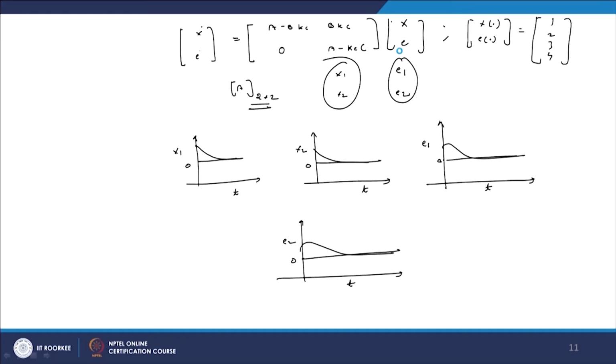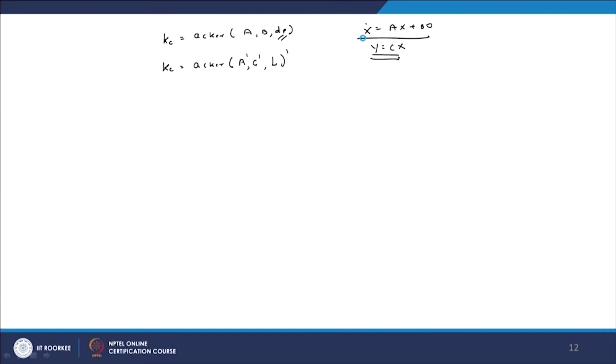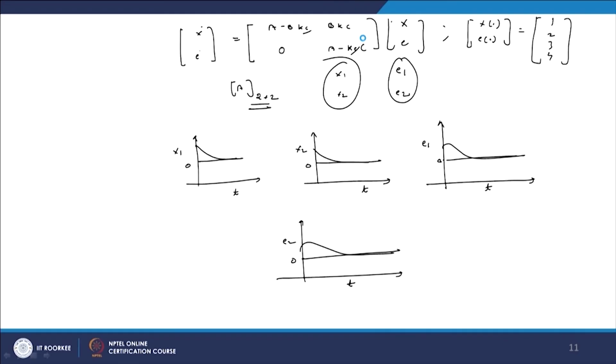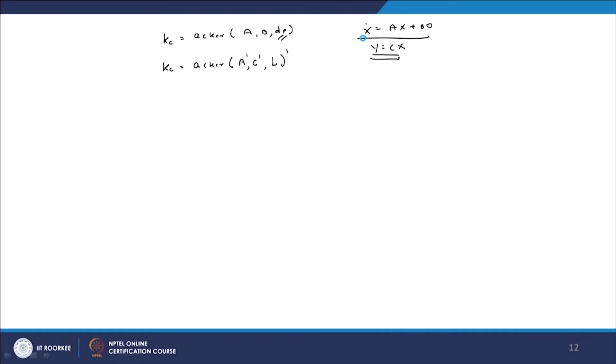So, as per this equation about the observer and control equation, we have got Kc and we have got the Ke. Now, we have to represent the complete system into the state space form, and therefore here the command we have to use is sys equal to ss.